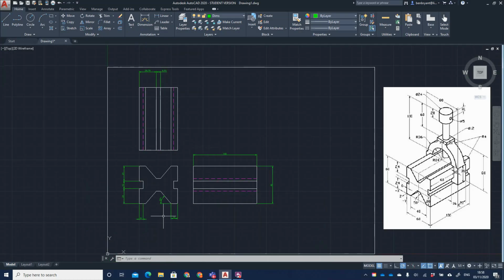So I've got a 60 by 60 by 100 mil block. I know that the middle of my V is 6.44. I know the edge shoulder to the inner part of my V slot is 26.78 millimeters. What I could do now is provide the angle or the length, but I have the angle as well. I could also provide the depth. So again, I could come along, click on snap points and just provide the depth of my V as well.